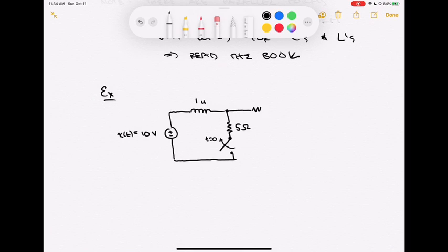I'm going to go through a resistor here, and I'm going to let this resistor be 2 ohms of resistance, something along those lines. And then I'm going to let this go through a capacitor, and that capacitor will tie down to that same thing. So I've got a pair of loops in here, one of which has a switch that is activated at time t equaling 0. The capacitance in this particular case, I'm going to let it be 1/5 of a farad.